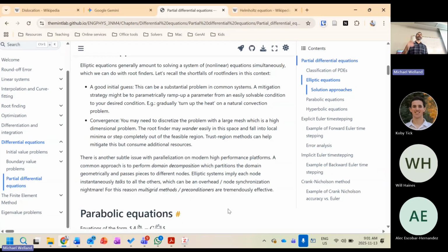If anybody ever encountered an error that said backward initialization failed when you're first running it, you probably didn't, but in case you did, that's what it was talking about. Your initial condition wasn't actually physically realistic, and it just had to smooth it out. Honestly, the smaller your time step, the closer your previous solution is going to be to your new solution, which is going to make that root finding algorithm faster and a bit more robust.